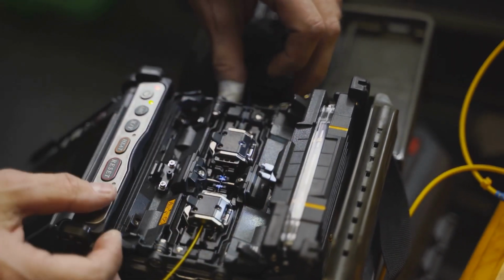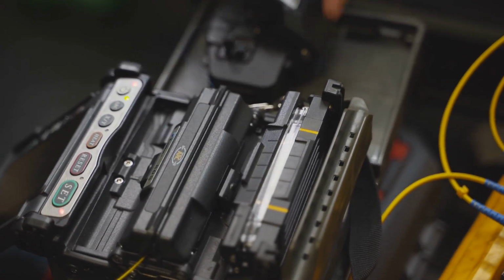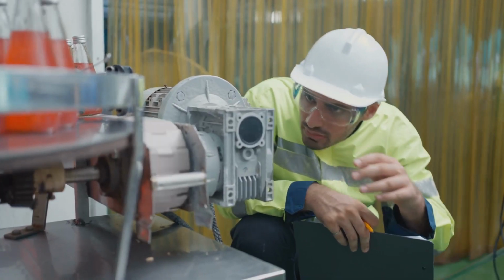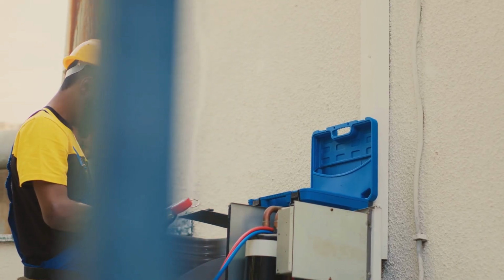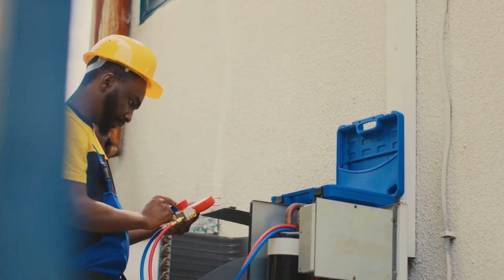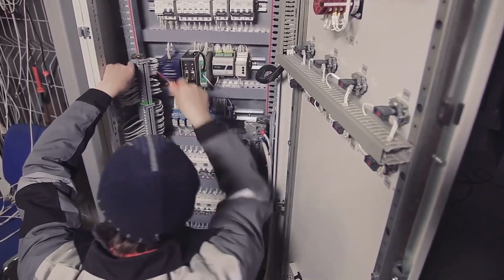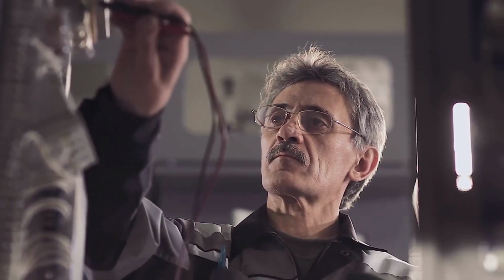Section 5. Fixing encoder issues. Back on track. Facing an encoder issue? Don't panic. Here are some troubleshooting steps to get things back on track. Check the wiring. Ensure all connections are secure and free of damage. A loose wire can cause major headaches. Look for any loose connections, damaged cables, or poor connections at the terminals. Tighten or replace any faulty wiring to ensure a stable signal.